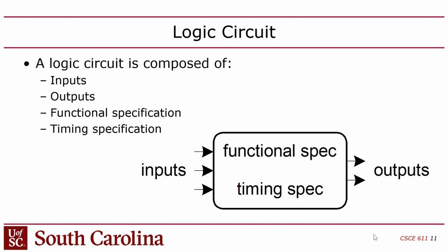Now, if you want to get crazy and say, hey, I think I ought to be able to run my CPU at 200 megahertz, well, then you can tell Quartus to achieve 200 megahertz, in which case it's going to take much longer to compile. And it may not be able to do it. You may have to go in and deepen your pipeline. You may have to design your code so you have a shorter logic path in each cycle from register to register. But we'll talk more about that at the end of the semester. So for this project, 50 megahertz, you generally don't have to worry about it.